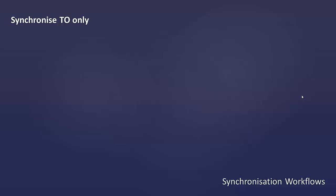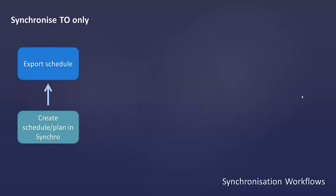Another option is the synchronize to workflow. So in this scenario, you would be creating your schedule directly in Synchro, and you would be typing your tasks into Synchro and using it as a scheduling program, which we do provide that service in Synchro. It is its own scheduling system. So maybe you're more comfortable in Synchro, but someone is requiring you to create an archive of that in a particular format, such as P6 or Microsoft Project. Someone who wants to be able to open that file on a different program and they don't have Synchro. What you would do is if you create your schedule in Synchro, you can export it to that program for them to open it up.